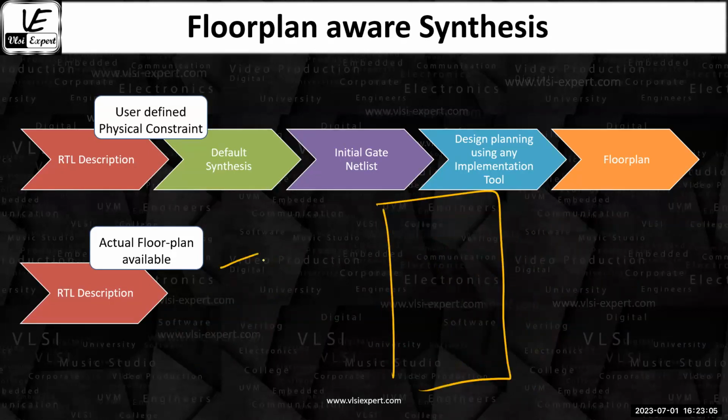So I'm saying this is a NAND gate, this is an inverter. This is a pin A, this is a pin B. I gave you a constraint that the pin A is going to be here only, and the pin B is going to be here only. This is the constraint, which is a physical constraint. Physically, in your chip, pin A is supposed to be at the top corner, pin B is going to be the bottom one. Now, why is this constraint there?